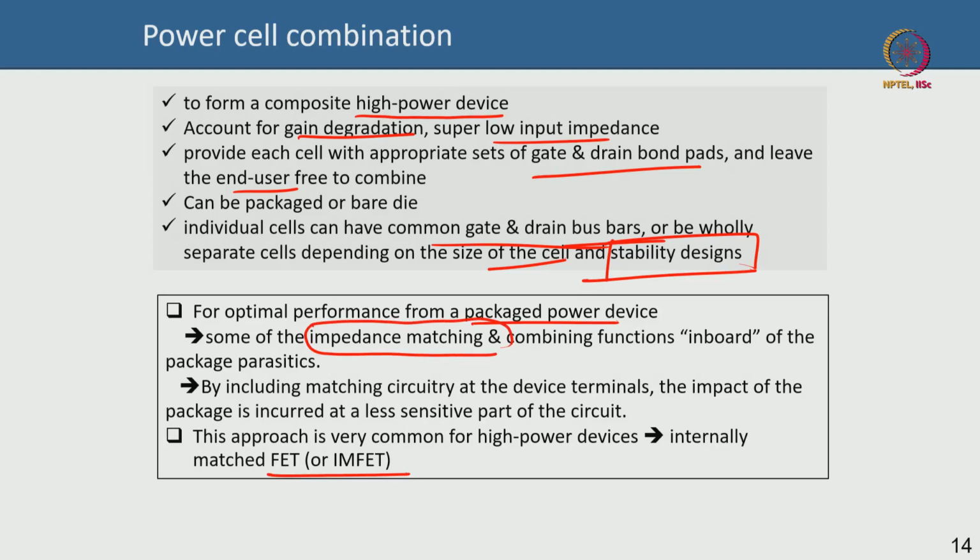It means that any device, when it looks at the output, will have some kind of impedance. Impedance is a complex resistance, in the form of A plus jB. If you have done your undergrad engineering, you will know what impedance is. It considers the magnitude and phase, and it is a complex number because you have capacitances and inductances, so it is a complex version of resistance in a way. When you have an impedance on the output of the device, you want to deliver power to a load, ZL.